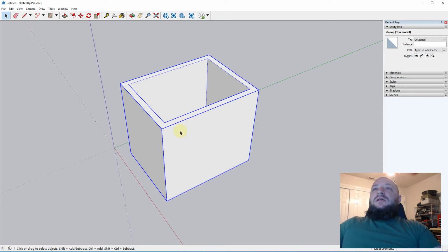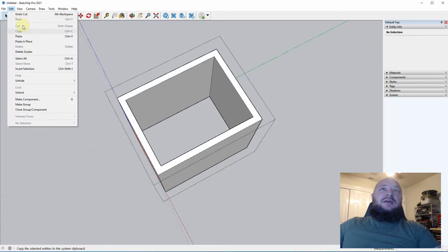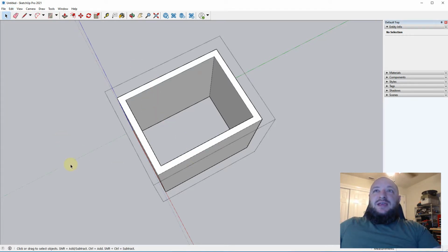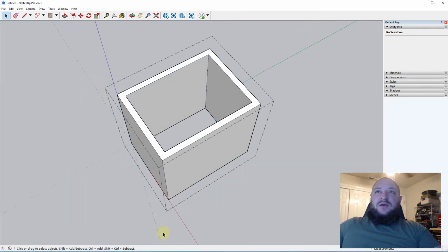All right. The next thing I'm going to do is double click in here. I'm going to select that floor that's right there, and I'm going to do Control X on the keyboard, but that's the same as going to Edit and Cut, and it's going to copy and delete. Then I'm going to hit Escape to get out of this. You see that there's this bounding box right here, that's indicating that I'm in some sort of group or other selection, a subset of something.